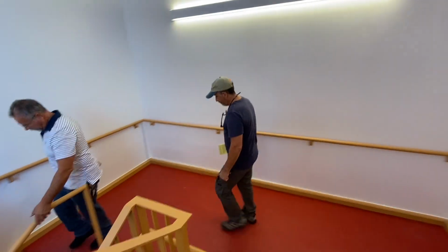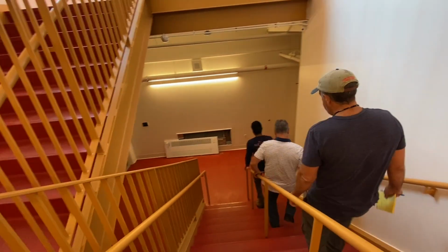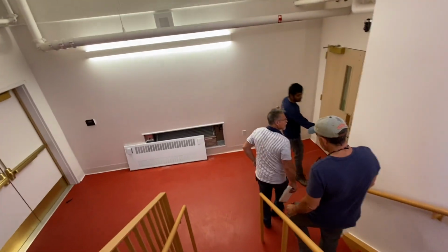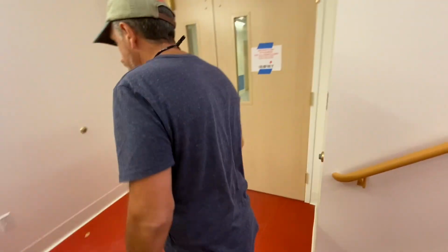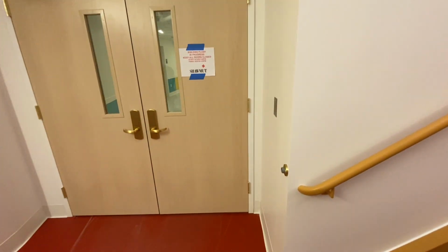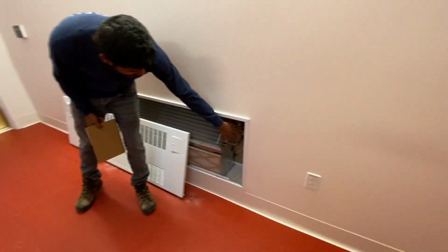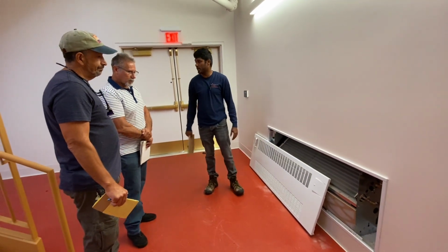So this is the unit heaters. They have it in all the spaces. This is the sensor here, the blank plate, and the set point is only from the BMS. We open the valves and the aquastat turns the fan on. And we get the fan current status.